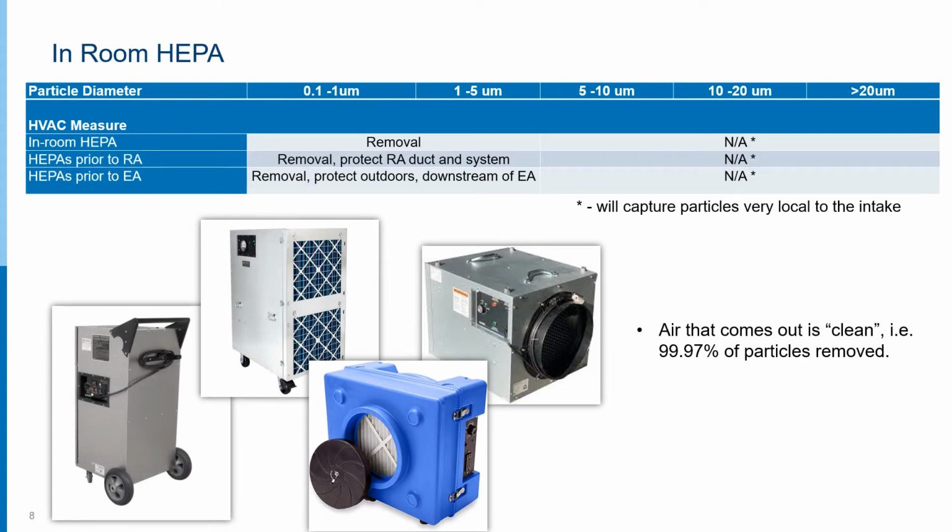Okay, let's talk about filters. There's been a lot of talk about HEPA filters here in the last 3 to 5 weeks. We usually design air across filters for about 400 feet per minute to 600 feet per minute. So most of the units that you see pictured here are somewhere between 600 and 2500 CFM. In a normal patient room, that can be a lot of ventilation. It's some capture velocity, but not a ton of capture velocity that you'll see at the inlet there.